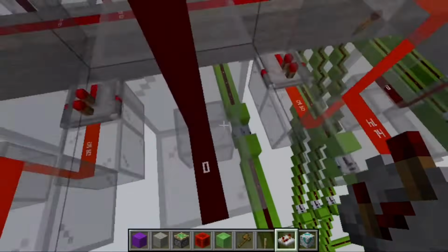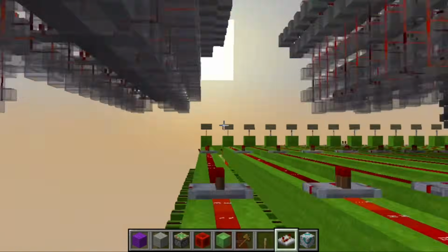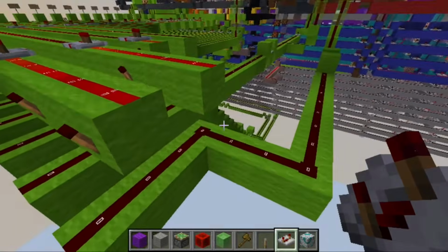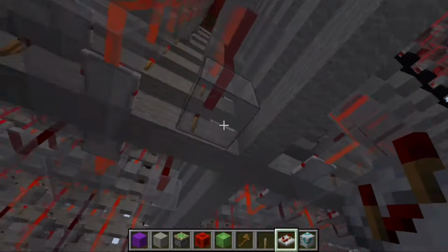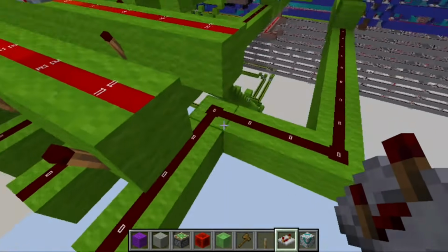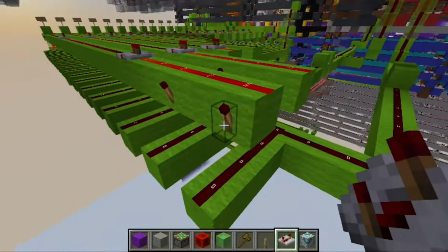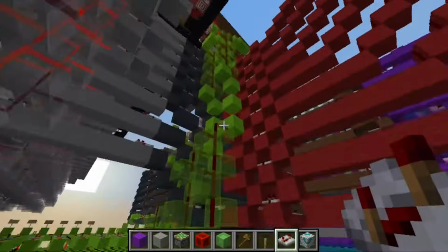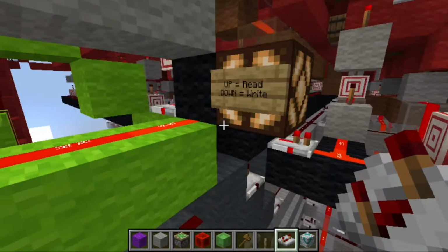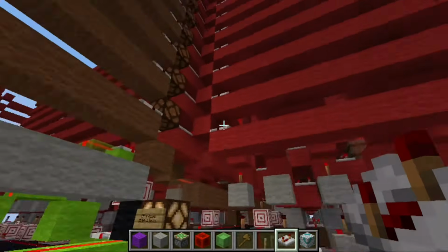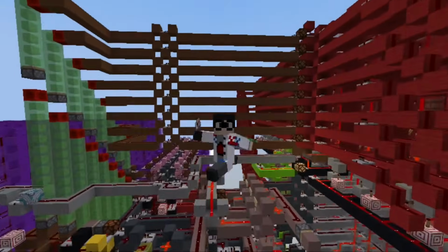For the second line, only the store operation is going to power it, not the load operation, because this is the read/write function of the data memory. For load, we don't want to write into the data memory, so we don't select it. But for the store, we want to write into the data memory, so we have to select it. And this line just goes to here, which is the input for read or write of the data memory. And yeah, that's pretty much it. That's all you have to do.